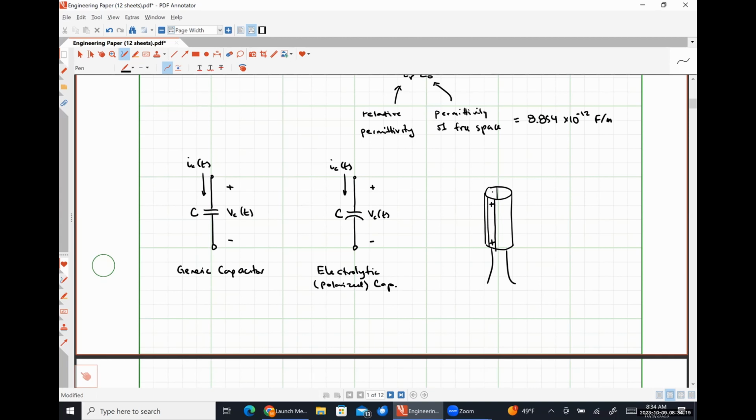The very top is usually a thin metal plate that's scored, so that if you ever disconnect or connect this electrolytic capacitor incorrectly, it's very easy to dissipate that extra energy. What's going on is a chemical reaction is effectively burning up all the electrolyte solution in there, and that scored top plate is able to deflect, which lets you know that this capacitor has failed, while still keeping all of the residual electrolyte inside of it so that it doesn't corrode anything else.